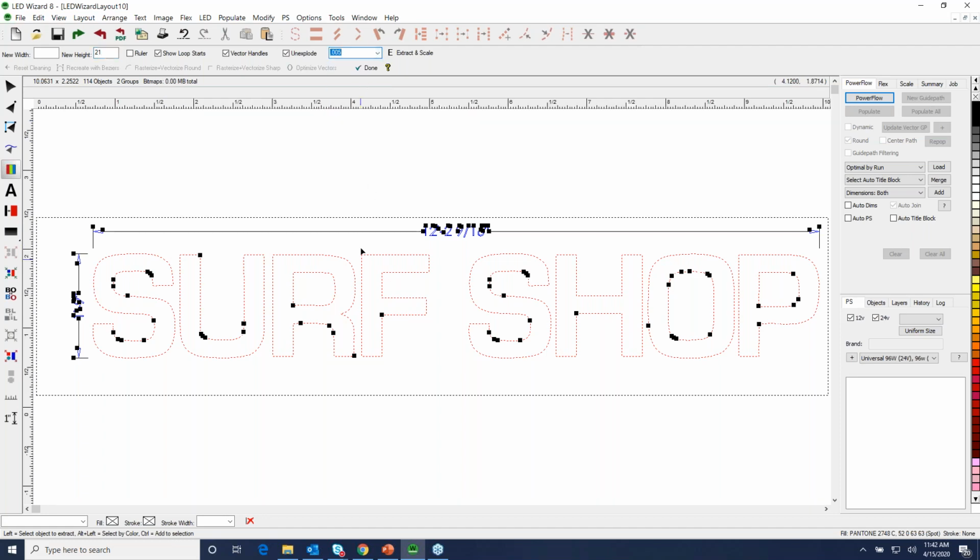And I mentioned before that we have this value. What this value means is that one point will look around for another point that it might want to connect to, and it's going to look around at a distance of 0.005 inches. It's a very small distance. A lot of times these files have points that are coincident, right on top of each other. This one's not quite as clean, but I tested it before, and 0.005 is big enough to capture and connect most of these. You don't want to do too big of a value because then it gets a little bit crazy. So you want the smallest value that works.